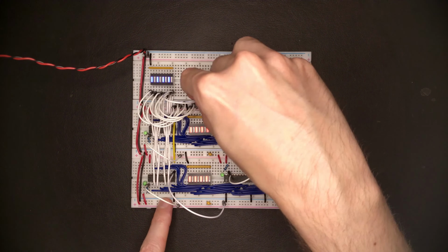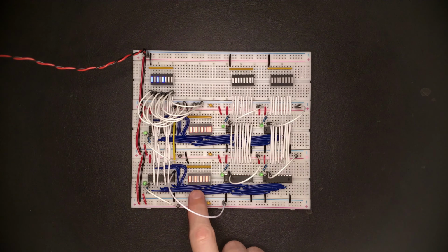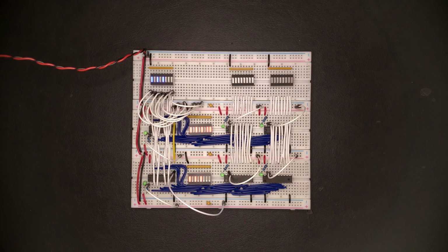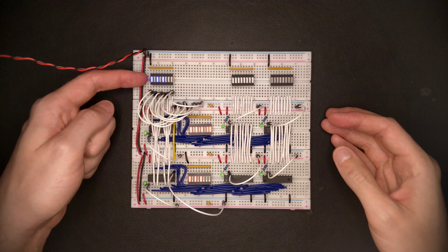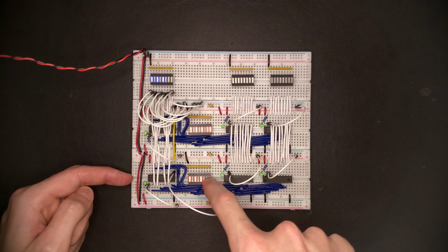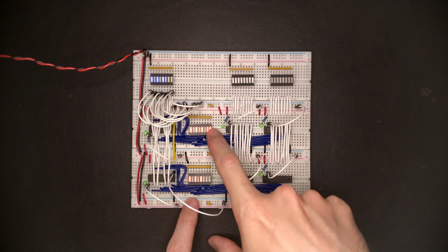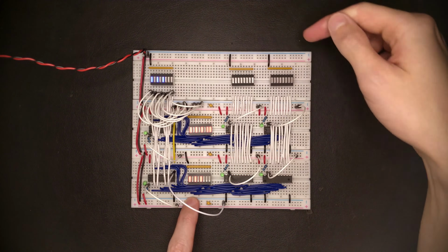And now we can have a different pattern and store this into the second register by enabling that for writing and toggling the clock. And there you go, the value has been stored into the second register. So basically, this allows us to present a value for the register file to store, and then we can pick which register should store the value, and it gets properly latched into it. And the read circuit here on the right allows us to pick which of these registers get to put their data onto the read data outputs of the register file.